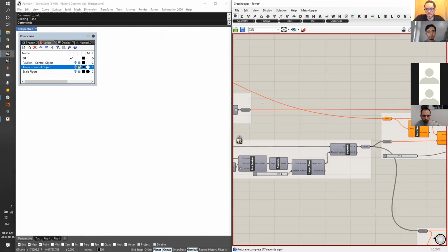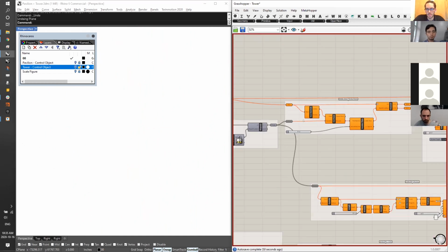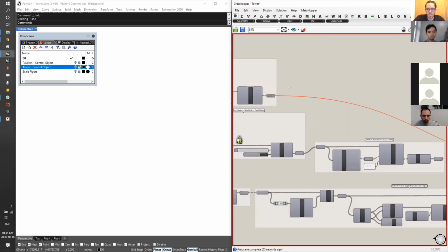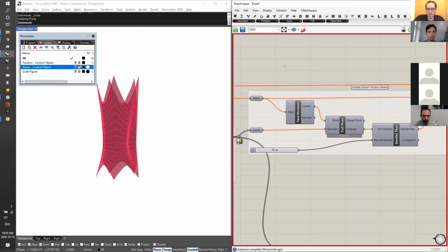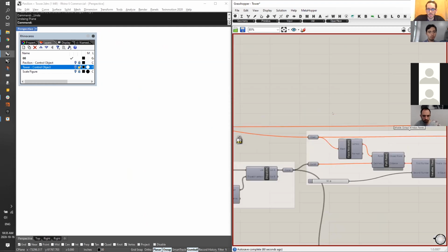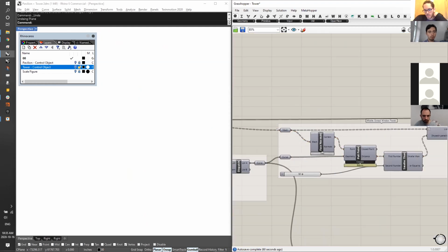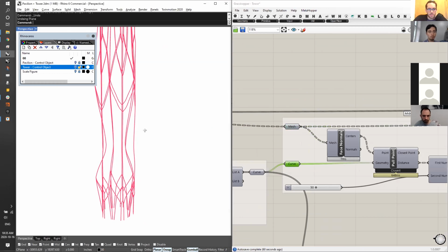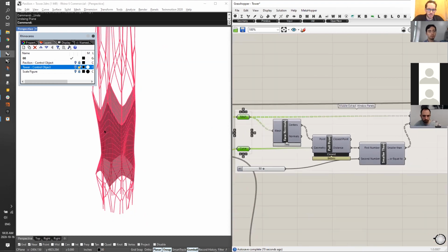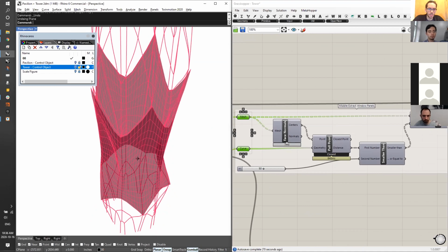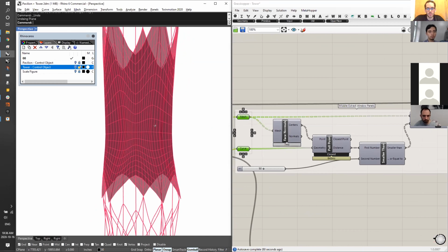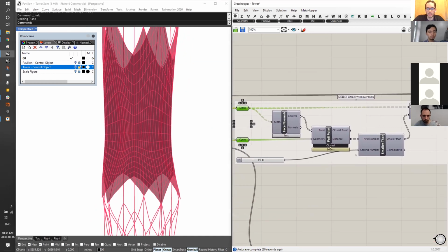Okay. So now we're going to turn on a couple of different elements here. Turn this on. Turn this on. So in the section that's called middle extract window panels, we're going to take the middle portion along with these derived curves, and all we're doing is getting sort of an attractor. In other words, whichever given panel is closest to the curve will be kept. Whatever panel is furthest away will be removed for other purposes. And we're going to give it some sort of distance threshold.